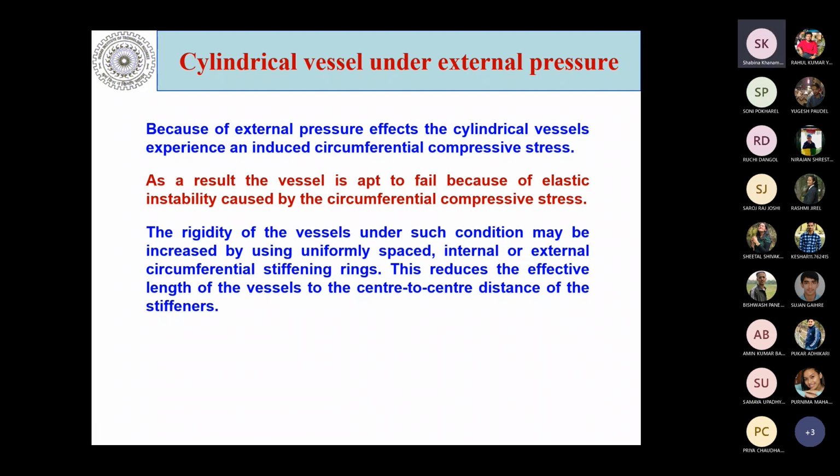These stiffening rings will reduce the acting area of this circumferential compressive stress. So this reduces the effective length of the vessel to the center distance of the stiffeners.